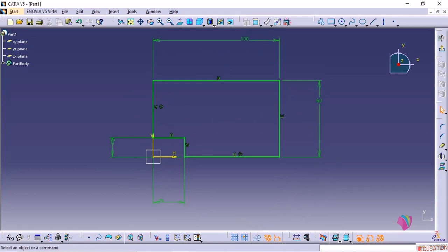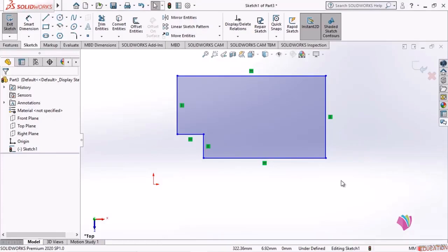Now this boundary we will constrain in Solidworks. The procedure that I have followed in CATIA, I will use it here in Solidworks. Your job is to see whether the same process is applicable here or not, so that you will have a clear idea on the technique and not the tools. Tools are just the things which are there for implementing the techniques. You have to learn the techniques. First in CATIA what I have told you is you have to create the relation with the datum axis.